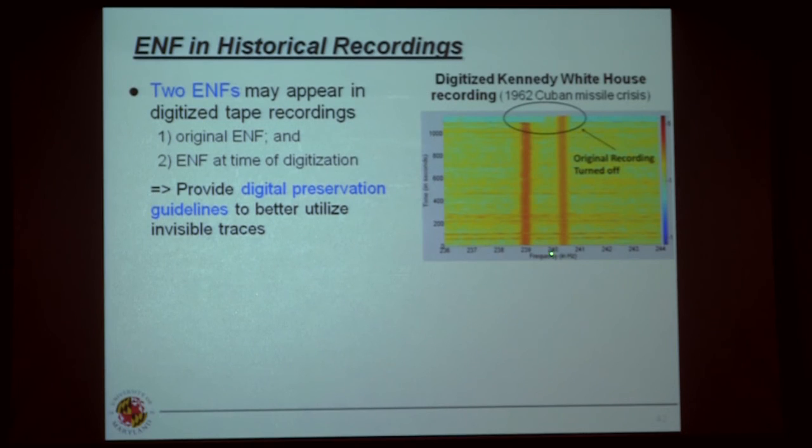We are actually looking at the fourth harmonic here of our 60 Hertz grid. This could be most likely coming from the original recording time, and the other one coming from the digitization time. And you can see that this separation tells us the recording speed of the tape and the digitization playback speed are not exactly the same, and that is making it separated.